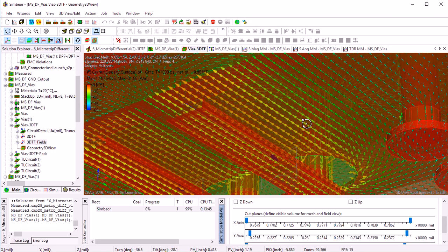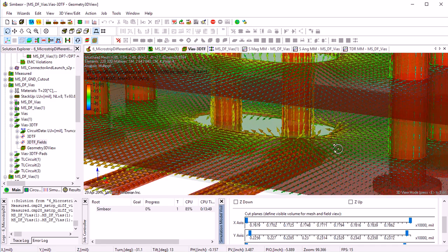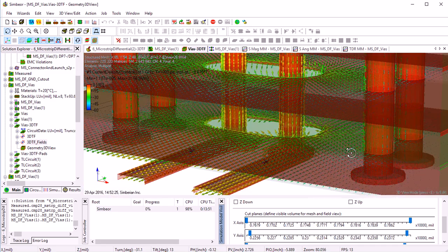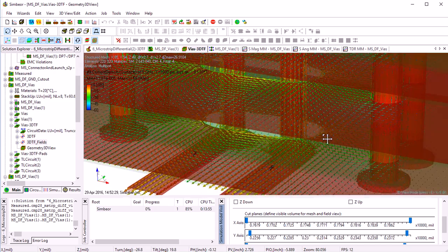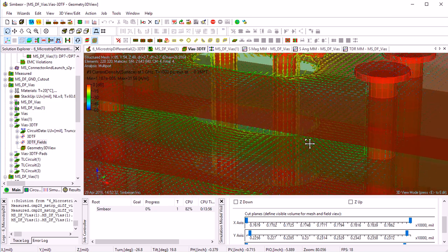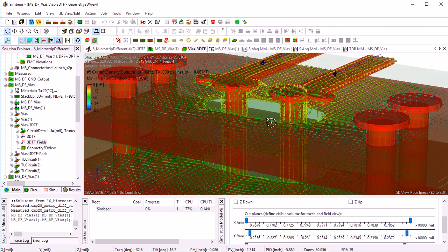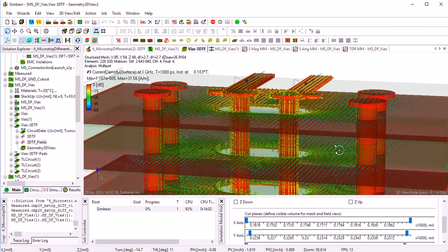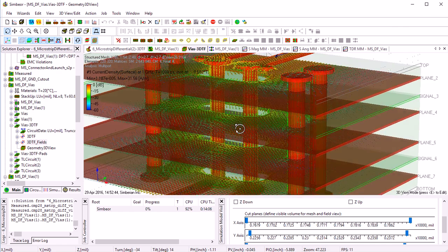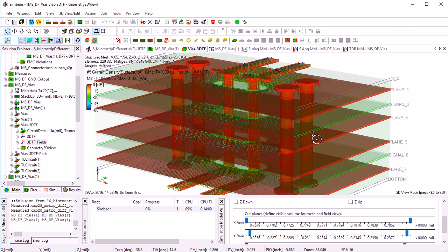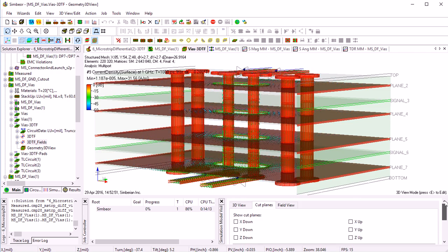You can see how currents are flowing nicely, getting into vias. On the other side of the plane, currents are flowing in different pattern, and then you can see through the vias and to the top, and they are kind of going through those structures. Notice that there is some current flowing on the stitching vias and no currents flowing on the sidewalls that are electric conductors here, perfect electric conductors.